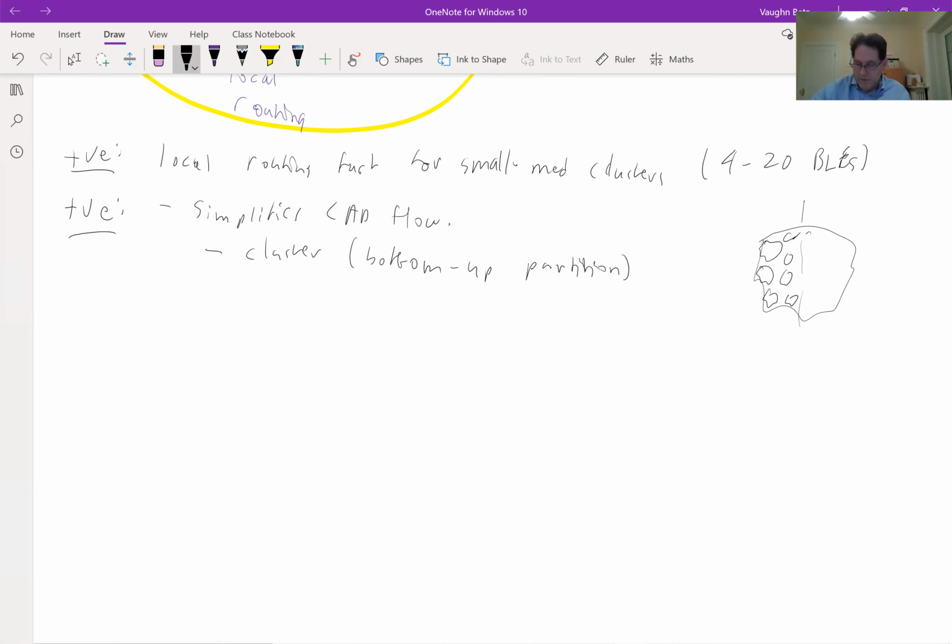So instead of cutting in halves and then quarters and so on, it'll look at the little things and start gluing them together because instead of having 100,000 little things, it wants 10,000 medium things. Clustering can be quite good at that, where it glues together the little things instead of chopping up the circuit into smaller and smaller parts till you've got it chopped into 10,000 parts. And clusters work pretty well too. So we can do this bottom-up partitioning to form logic clusters.